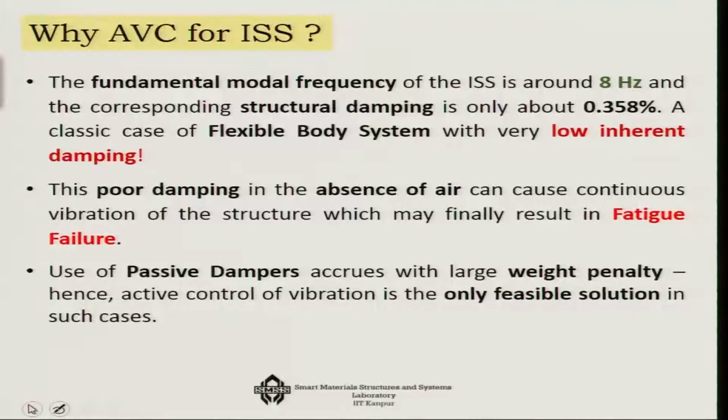The fundamental modal frequency of this International Space Structure is about 8 Hz, and its structural damping is phenomenally low, only 0.358%. So, this is a classic case where you have a flexible body, 8 Hz fundamental frequency is very flexible, and once the vibration starts it would not stop because the structural damping is very low. It has a very low inherent damping.